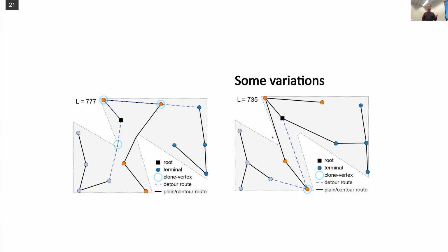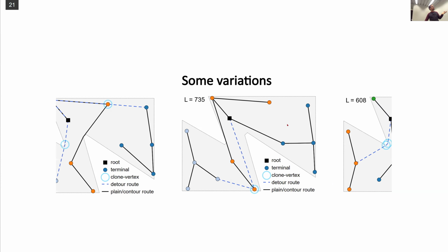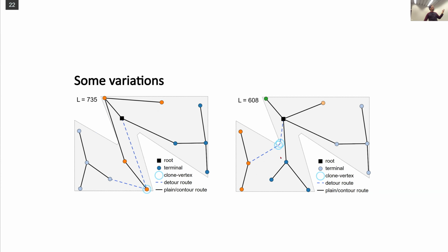And if you further relax another constraint that is in effect here, which is to use the minimum number of feeder cables. For 12 turbines at 4 maximum capacity, it would be 3 cables. That's what is reaching the substation here. But if you still respect cable capacity but allow more feeder cables, you can have a further reduction, where you connect some directly to the substation and then the others in clusters of 4 and 2 or 3.